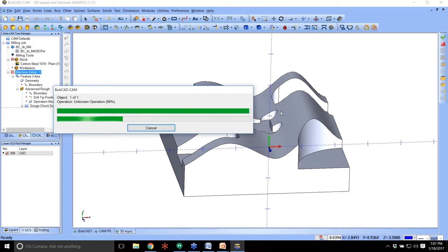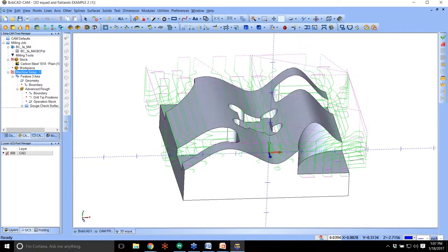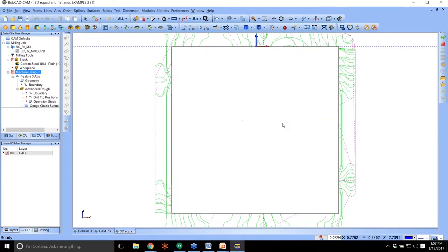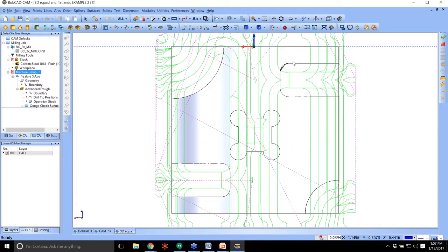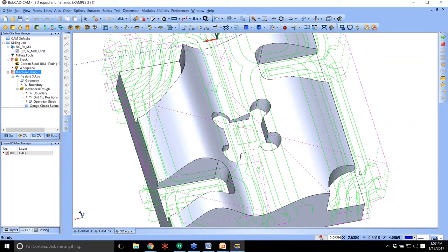And this is where it comes down to that aspect. We actually have a question on rest roughing. We're going to use it on this particular feature, okay? So if you guys look from this view, okay? We can see that we're machining everything pretty nicely. It's cutting past those walls, which is really nice. That way you guys can get right past that wall.